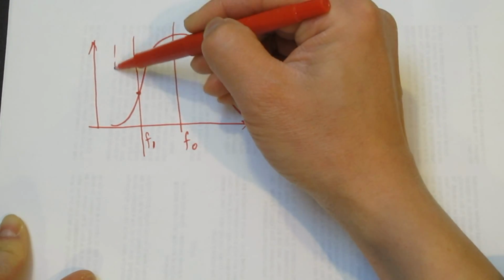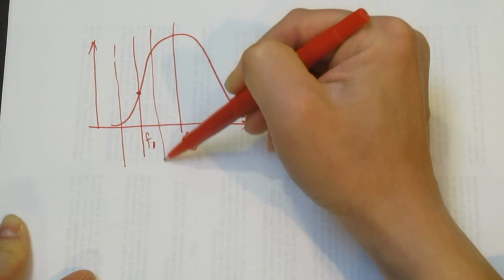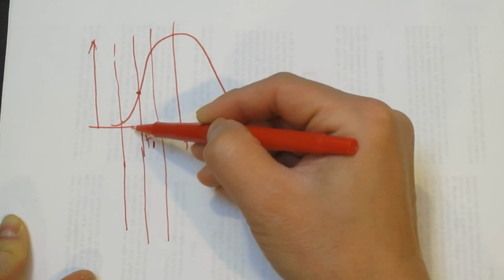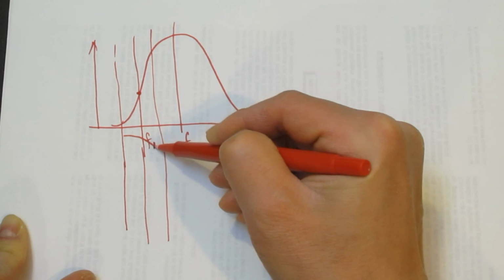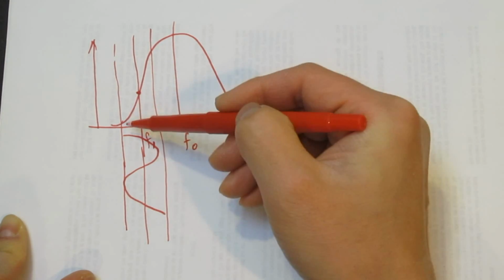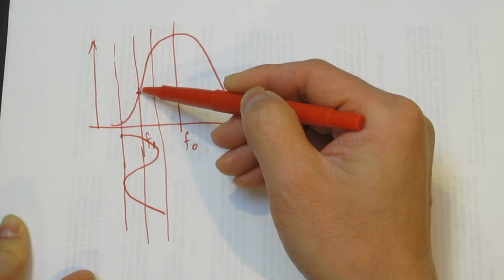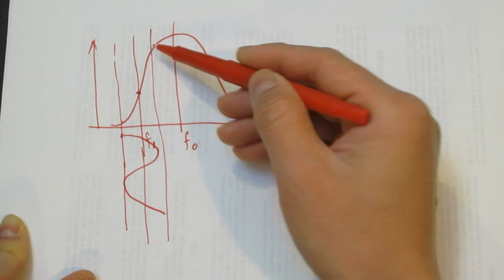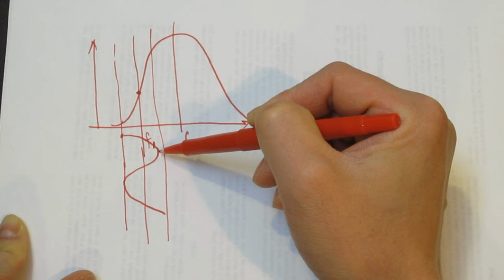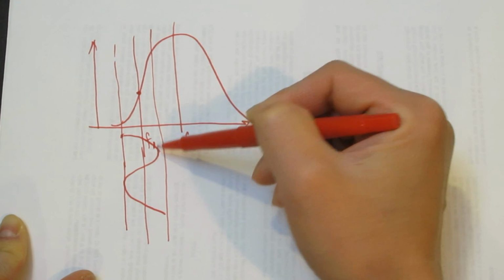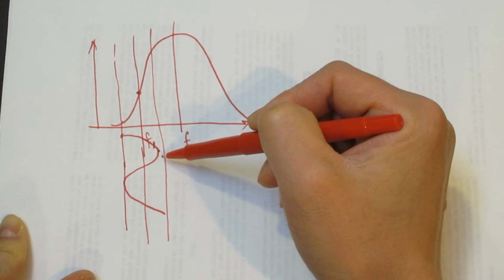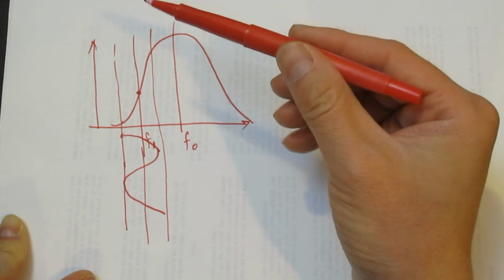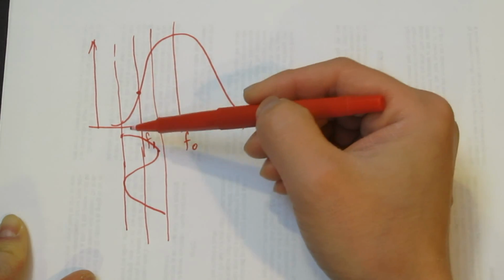So then what happened is, if we draw this down here, if the frequency is low, then our signal output in relation to this reference point is going to be negative. If the frequency is high, we're going to have an output at this point, which in reference to that reference point will be positive. So utilizing this slope of the transfer function of our bandpass filter, we can also demodulate